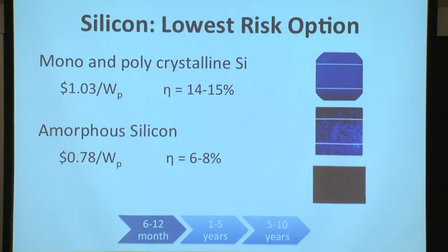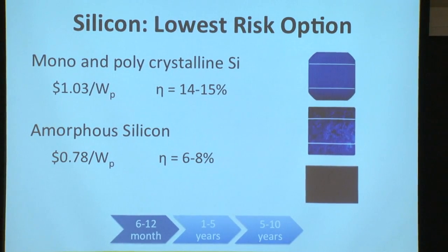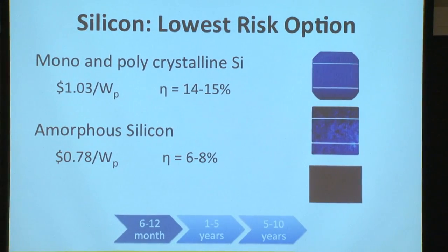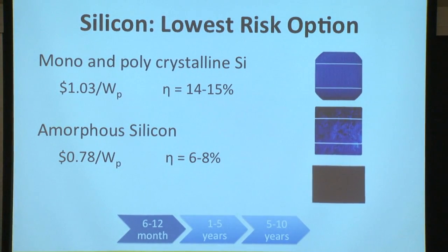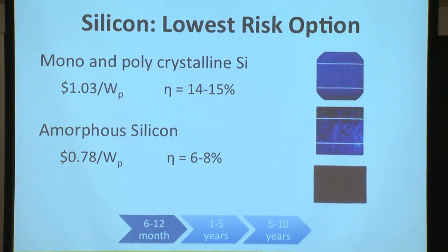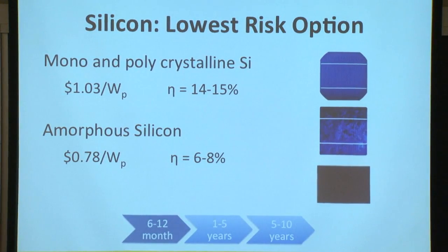It's important to note that in the Lighting Africa project, because the lifetime of these devices is not limited by the photovoltaic component, but rather by the LED, the CFL, the battery, it opens up an interesting opportunity in that the photovoltaic component doesn't have to last as long as an installation you might put on a roof in Cambridge. It could only maybe be 3 to 5 years in lifetime, and for that reason we could decrease the cost of the encapsulation materials, the commodity materials, the glass, and the backing that would normally be required. So amorphous silicon might be a better opportunity in this application.